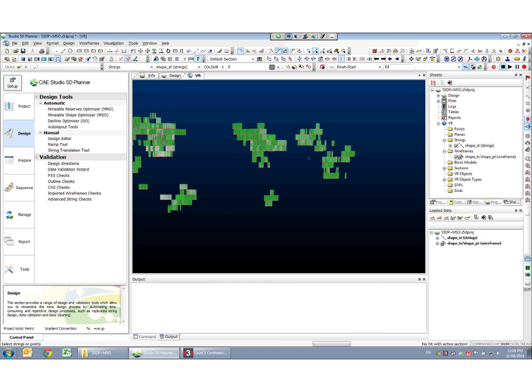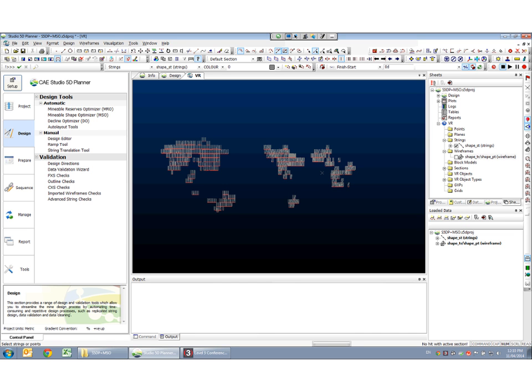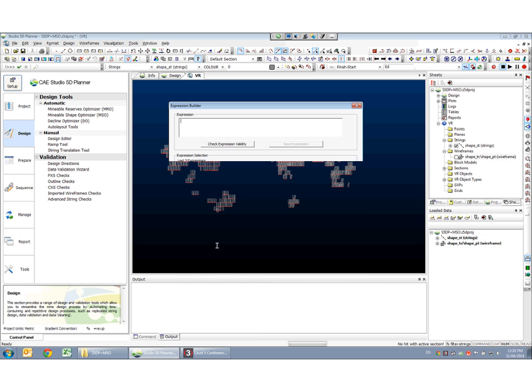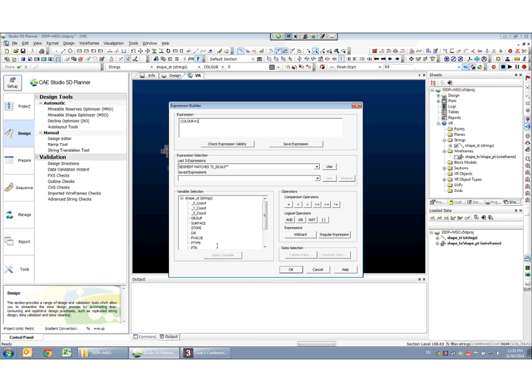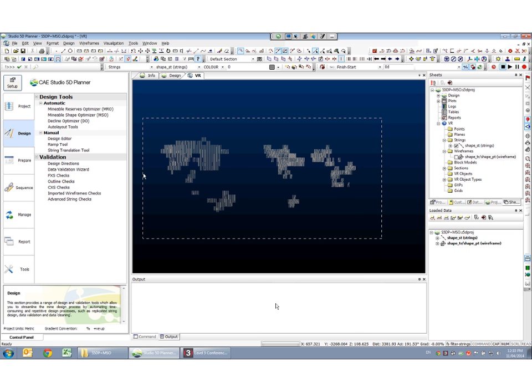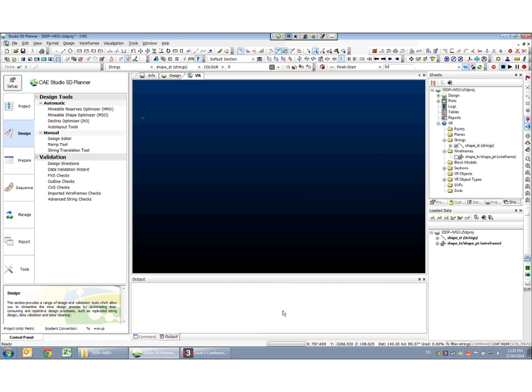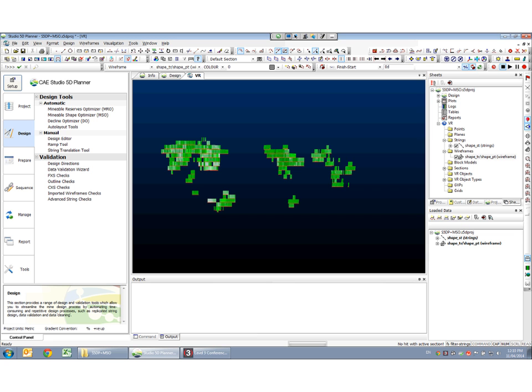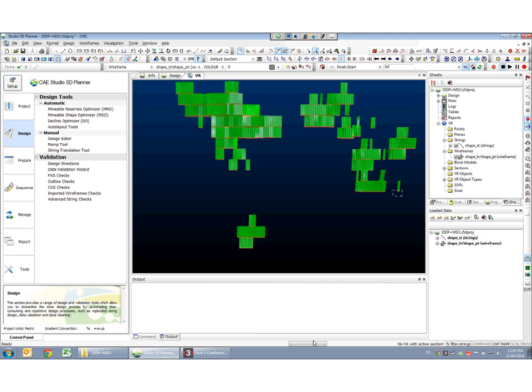And filter those, and I happen to know that they're colour 1, and we'll just get rid of all those. So I don't want them for what I want to achieve. So now what I've got is a floor string for every stope. And what I can do is, I want to get rid of that one. I can go and delete the strings for any of the stopes that I don't want to keep.